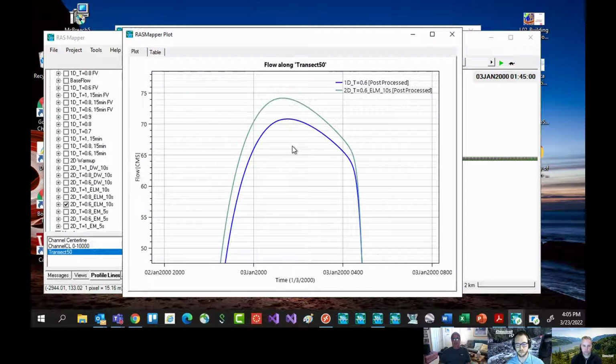And it uses what's called tracking to track upstream to find the change in velocity. So you have a face at a cell, and it tracks upstream to find where spatially this velocity started, and how far it traveled over the time step, and what the velocity was at the beginning.